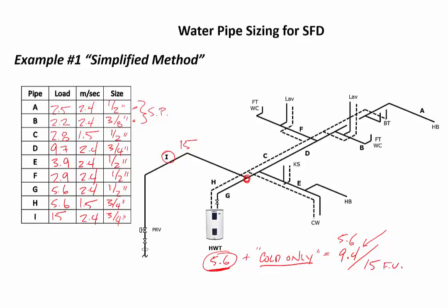Okay, so that system's sized. We've got our supply pipes as minimums from table 2632A. All our loads we also got from table 2632A, and all the distributions serving 2 or more fixtures for this installation, table 2634.